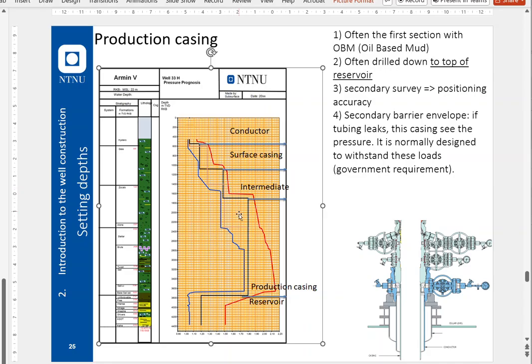The mud is not okay with that, but the problem is kick tolerance. So this is very obvious with regards to the strength in the red line and the mud, but it's called kick tolerance, and the regulations are internationally set that all sections should be able to take 4 cubic meters of reservoir fluid into the wellbore while drilling and still be able to maintain integrity.